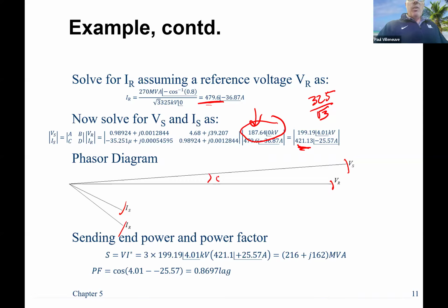So, and real world transmission line planners look at this all the time. They pick their reference voltage as a fixed value. So it's at 0 volts. And then if VS is a positive theta over there, that means real power is moving from the sending end to the receiving end. Okay. So just by looking at the phase angle difference between the receiving end and the sending end, I can tell you a power flow or estimate what the power flow would be.